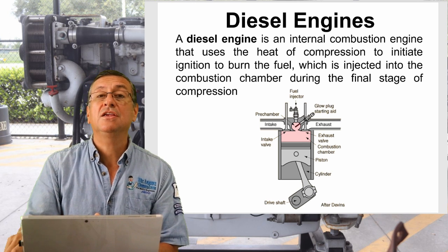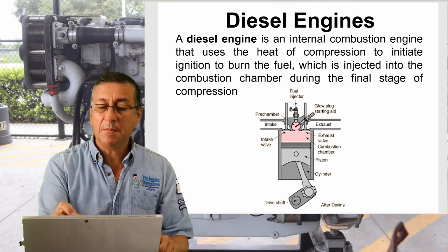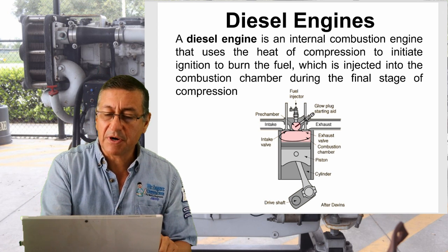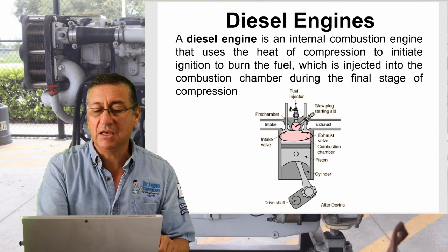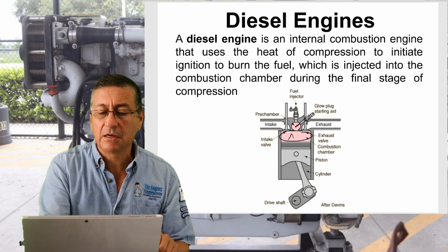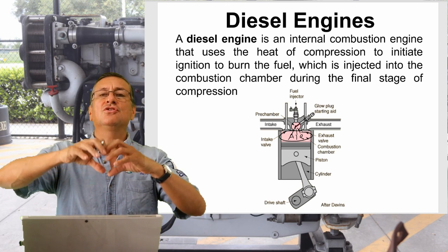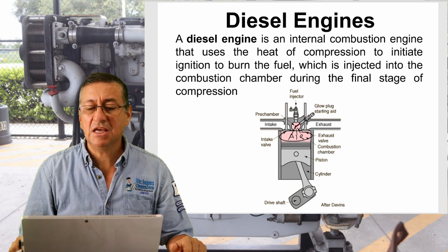But in the diesel engine, you need the air fully compressed. In this moment, in this combustion chamber, when the piston is finishing the compression stroke, you have pure air. Immediately after the piston finishes the stroke, the injector sprays the fuel and the ignition is produced. You don't need a spark plug.